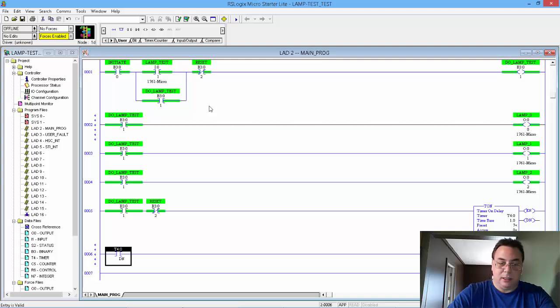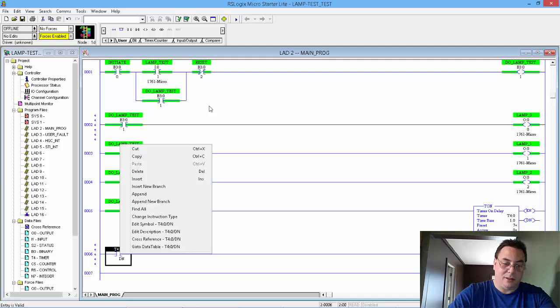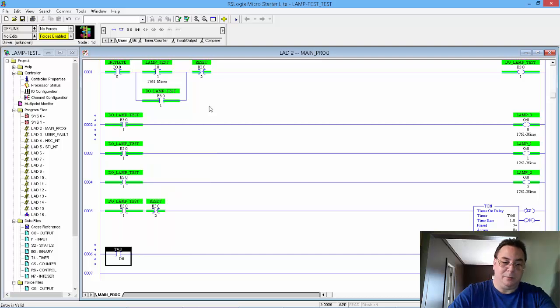Okay, so here we are. We're doing a lamp test. The timer times 7 seconds. This closes. So we'll actuate that. Oh, you can't, because we're not emulating and it's not running in a program. And once again, you cannot force these timers or toggle them on or off. But at any rate, this is closed.